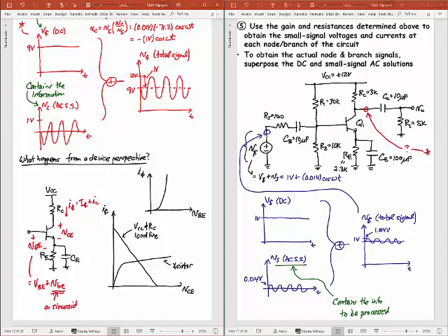With this, let me now put those things on these plots, so you can sort of see visually, at least from the IV characteristic, IV curves, which sort of describes the physics, what's happening in this whole thing. First I'm biasing up this transistor with DC bias current I sub C. Let's take this point right here. Project across there. That's my DC bias point, capital I, capital C. And I got that because I set my capital VBE to be some value, which is that value right there.